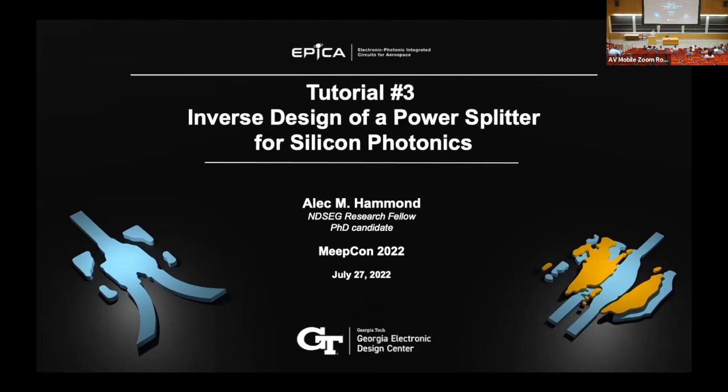The basic idea is you do what's called a robust optimization. You do a minimax or worst case optimization over various perturbations of your design field. So for example, if you expect the foundry to do some level of erosions or dilations, like over etching and under etching, you simultaneously optimize all three of those worst case scenarios. And the optimizer will produce a design that is tolerant to that, meaning it'll still perform well in spite of all those other perturbations. And I'll show some really cool experimental results on that tomorrow. So yeah, great question.